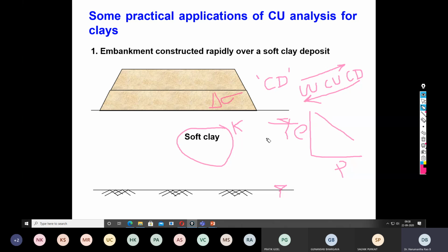So your consolidation is also an inherent function of the permeability. But permeability is directly proportional to the void ratio, or the density of packing of the particles. More consolidated means less permeable. Since the soil is already consolidated, we can't expect much permeability.